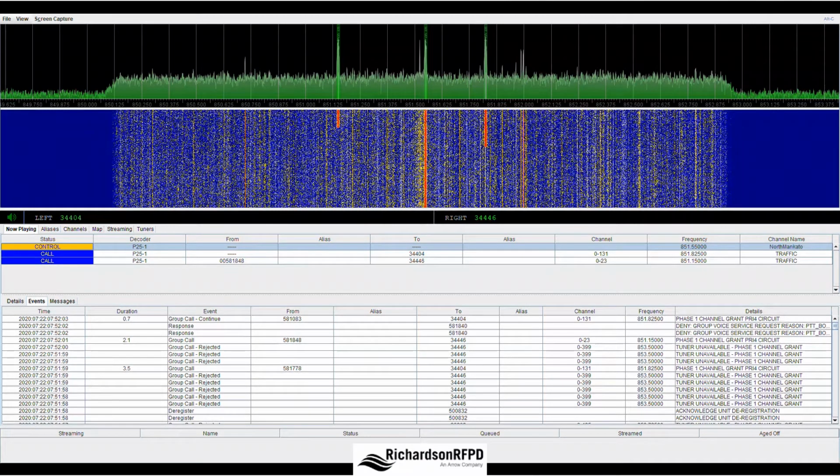The ADRV9002 is configured as a wideband receiver, sampling up to 40 MHz of the UHF spectrum used for police and fire safety. The sampled IQ data is converted into multiple narrowband 12.5 kHz channels. The following shows the wideband spectrum along with active narrowband 12.5 kHz signals.